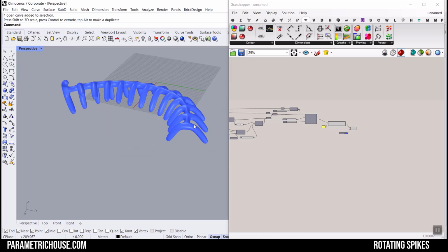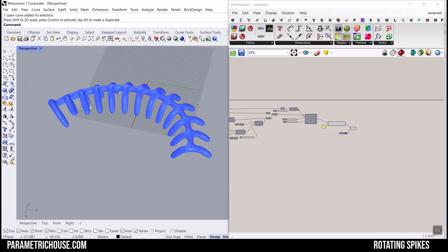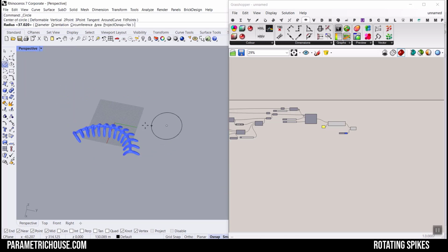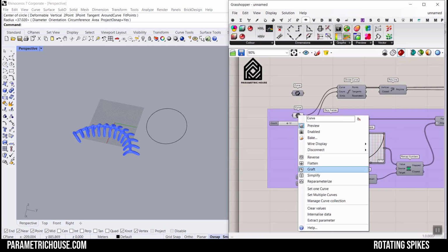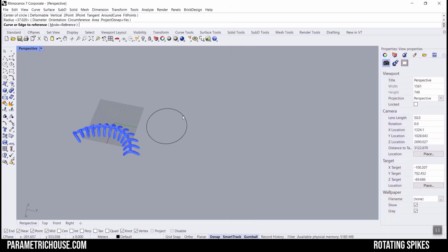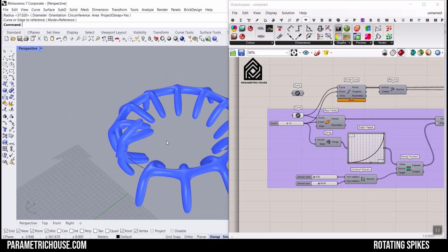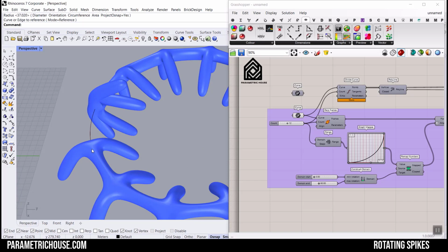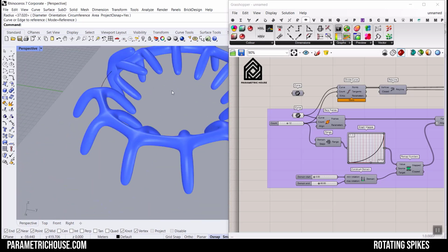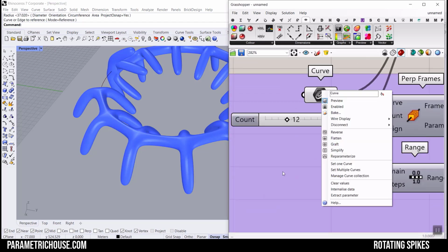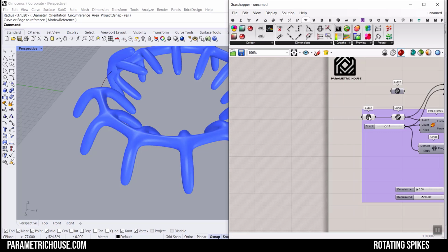But if you want to make this on a closed curve, what if I wanted to make this on a circle? How is it going to help me to work on a closed one? Because we don't have the closed connection, we have an extra polyline here. How can we fix this? This is going to be easy. Let me just right click here and extract the curve.